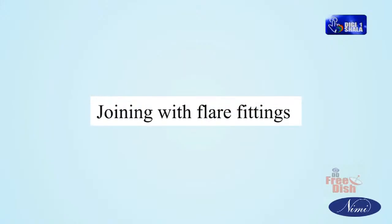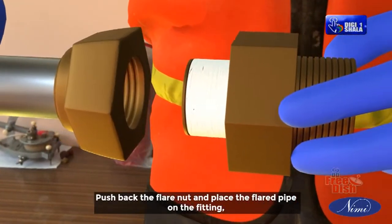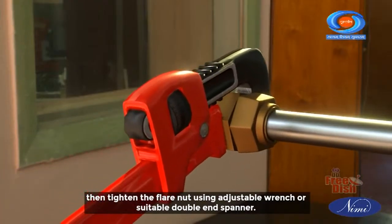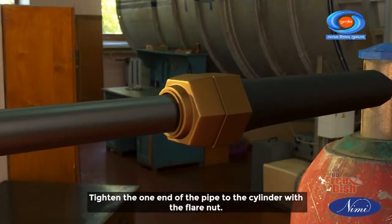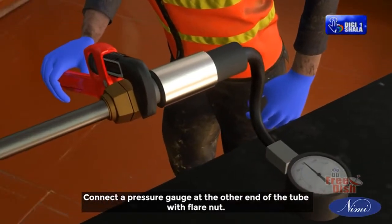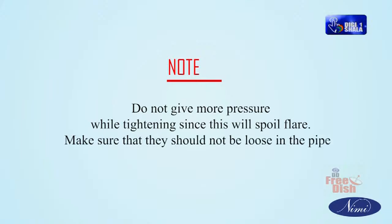Joining with flare fittings. Put thread seal tape on the thread. Push back the flare nut and place the flared pipe on the fitting. Then, tighten the flare nut using an adjustable wrench or suitable double-end spanner. Tighten one end of the pipe to the cylinder with the flare nut. Connect a pressure gauge at the other end of the tube with a flare nut. Note: do not apply more pressure while tightening, since this will spoil the flare. Make sure that they are not loose on the pipe.